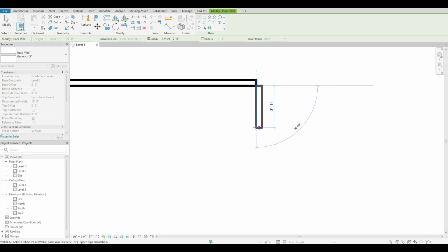And that's why your location line is so important, because if I am planning for this next wall, let's just say I needed 20 feet, and I just type in 20 feet, but it's starting at the wrong location line to actually really be 20 feet within the interior of that room, then that's where that location line really comes into play.